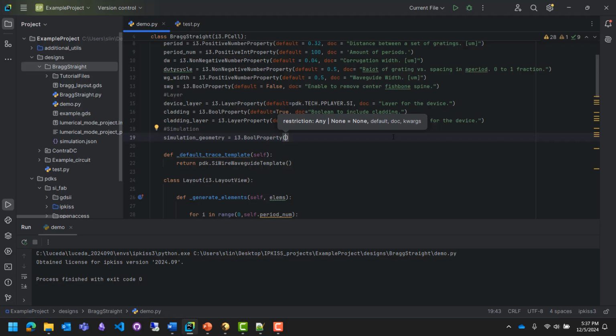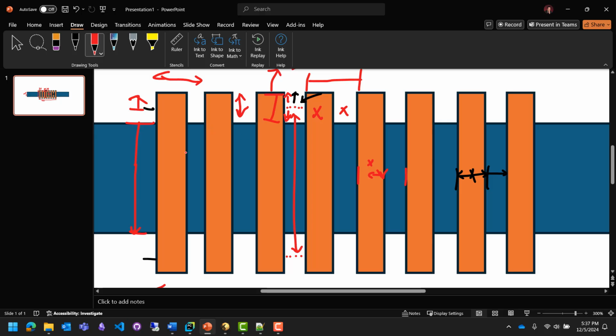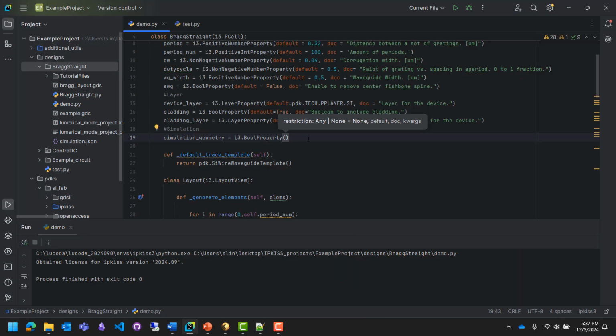There are better ways to simulate, especially for the Bragg grating in this example. We're going to leverage the Lumerical EME solver, so we won't have to draw the full device length. Instead, we can just draw a unit cell, for example, something right here like this, and we can artificially propagate it as many times as we want to represent how many cells there are. And that's a way more efficient way to produce your simulation results than it is to draw the full thing.